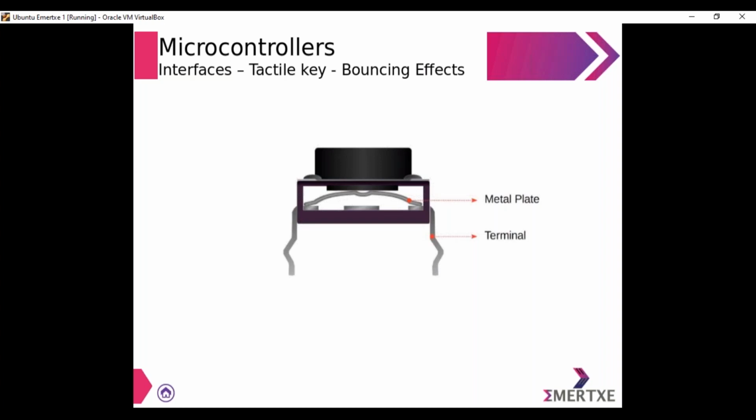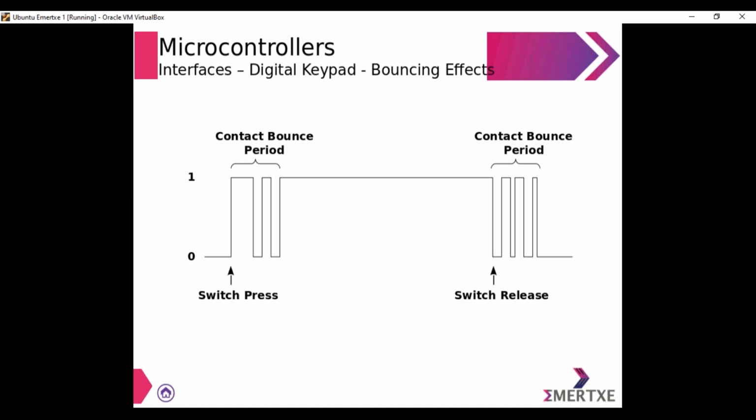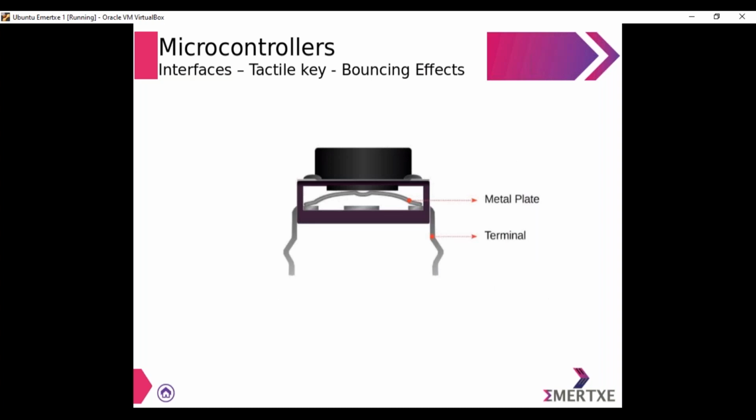So you have to avoid this bouncing period. You can see this is the bouncing period, which varies from 20 to 50 milliseconds when the switch is pressed and when the switch has been released. So you have to take care of it in the software only.